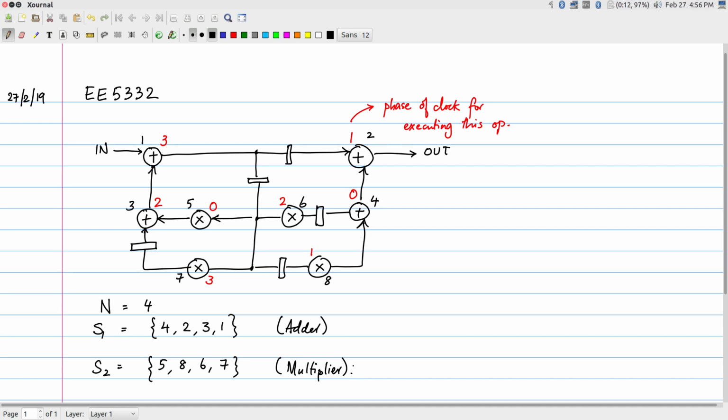What it is showing is only the connections between the different nodes, the dependencies, and also how many delay elements, sample delays, are present on the edges that link different nodes. Because of that you need to interpret this a little bit carefully. What I mean by that is, for example, this line that I have drawn in magenta over here corresponds to one edge in the data flow graph. This is the edge from node 1 to node 6